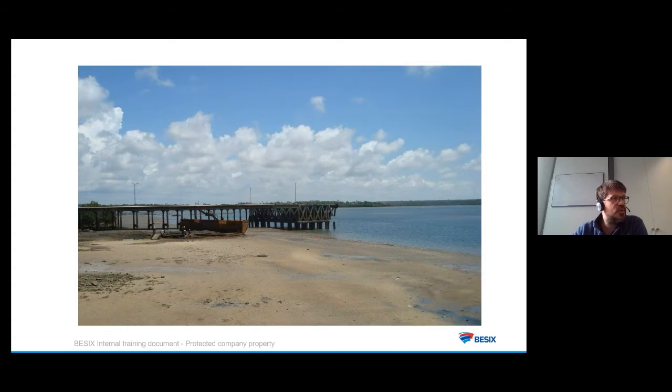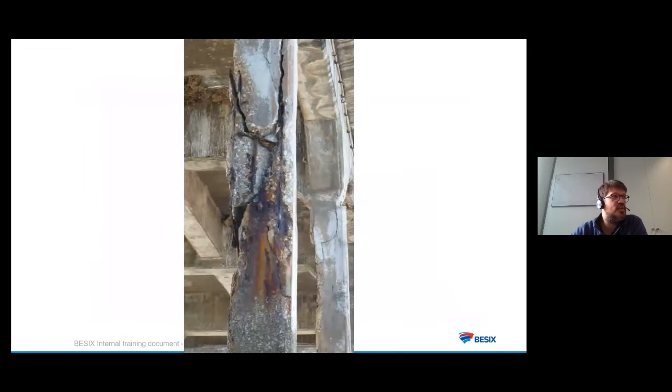And first, when you see this picture, it looks quite nice because it's in a nice country. But again, if you look a little bit closer, you will see things like this. You will think it might be a problem to refurbish this. Maybe it looks like there's a lot of damage. But anyway, this is still a possibility. You can cast new concrete, you can clean the rebar, replace the rebar if it's necessary or not.